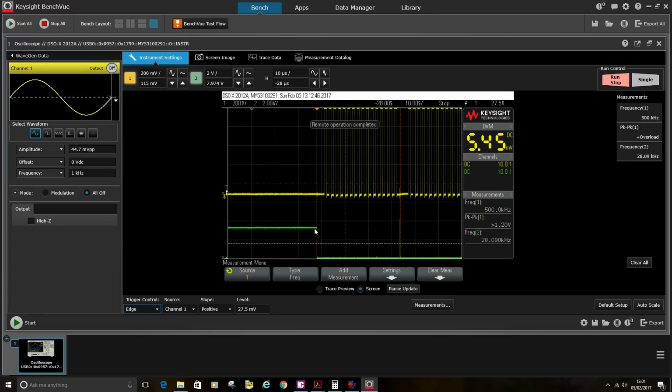Right, this is our chip select. So we bring the chip select low, or frame select. And then this is the SPI, so it generates its own clock when you do an SPI write. So there's 16 clock cycles, and it's idling low, 16, then a gap, except for these cursors, I can't see the frame select.